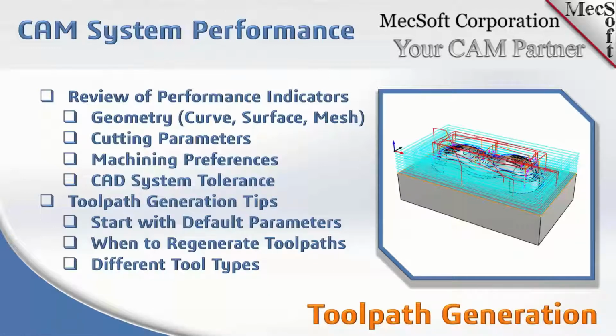This is my little tip here I put in here. You can start with the default parameters. Joe mentioned starting with a low density mesh. You can start with the default. Every toolpath you load, if you haven't run it before, it'll start up with default parameters. And those parameters, pretty much in all cases, will generate a toolpath. So you can do a quick generation with the default parameters with your geometry just to verify that, yeah, I'm getting a toolpath. It regenerated pretty good. Let's go in and start tinkering with that and getting it fine-tuned.